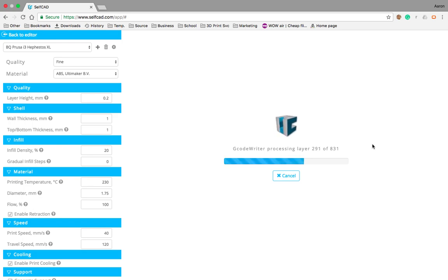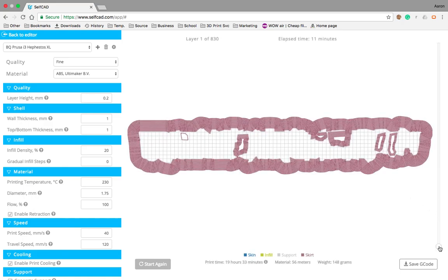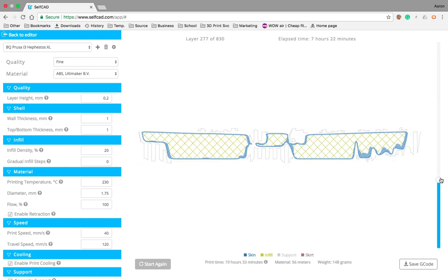If you have a complex geometry like the Hello Kitty one, I generally have to do the magic fix twice. I have to do it before the Boolean, because after the Boolean the magic fix will no longer work. It will destroy the object, because the object is so damaged that it wouldn't work anymore. So I first do magic fix, then Boolean, and then again magic fix, because it's still not printable.